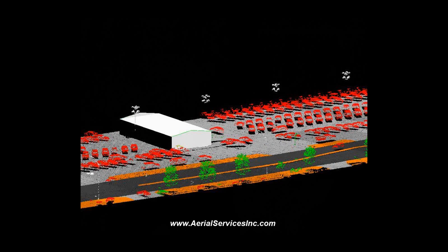Well, I think all three forms work the same way. They're all doing a point cloud of data. The high-definition scanners, where you point, click, shoot, then you move it, point, click, shoot, move, give millimeter accuracy, but it's really slow to collect everything. With mobile scanning, you're able to drive at highway speeds and collect data, but you're going to get a swath width of about 120 feet either side of center at somewhere between 600 and 1,200 points per meter, depending on the number of sensors they use.